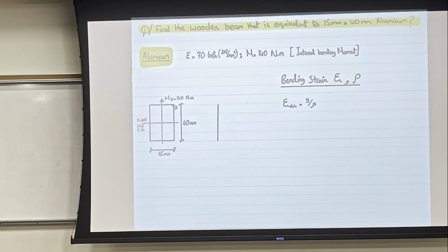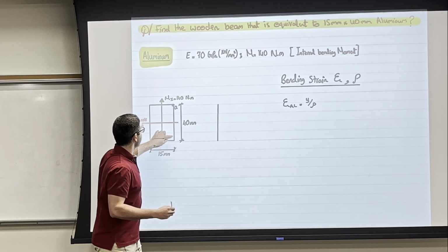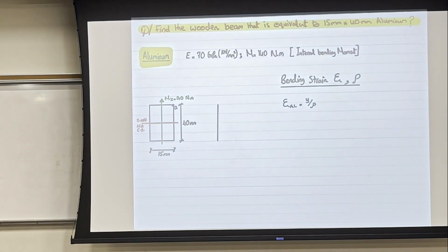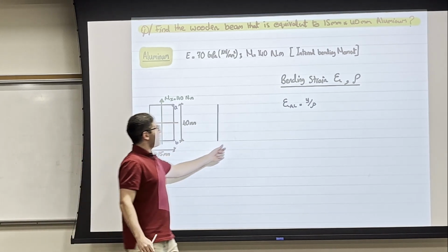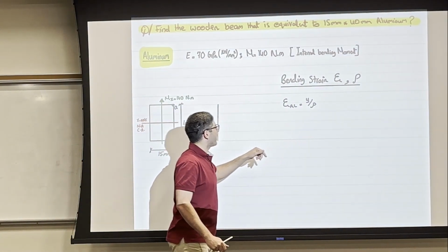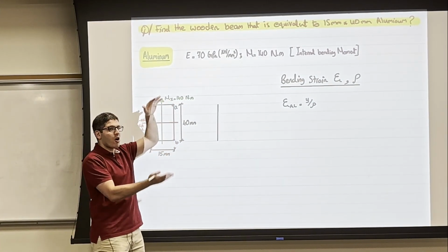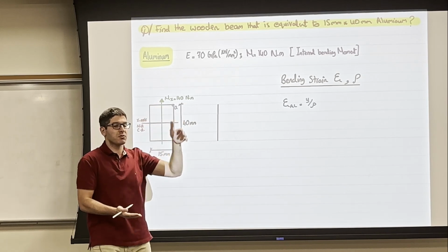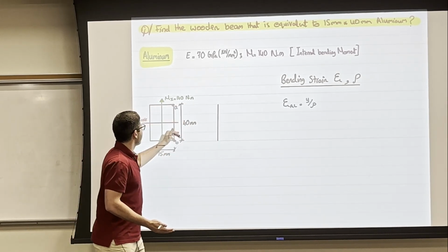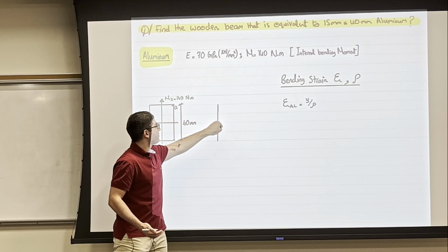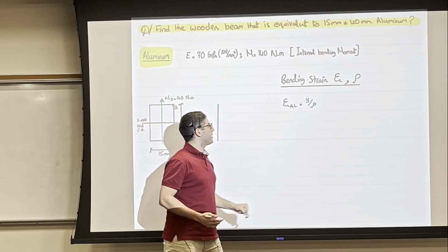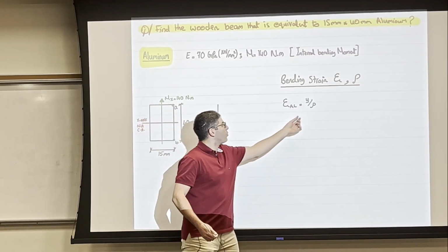I don't know what the rho is, and I will be calculating the strain at the ends, at A, and let me name this point at the bottom here, B. Because if you notice, epsilon is directly proportional to y, and from the previous lecture, the far ends of the cross section will have the maximum strain. That's why I'm interested in them. And of course, at the neutral axis, I'm expecting to have zero strain because y is going to be equal to 0.